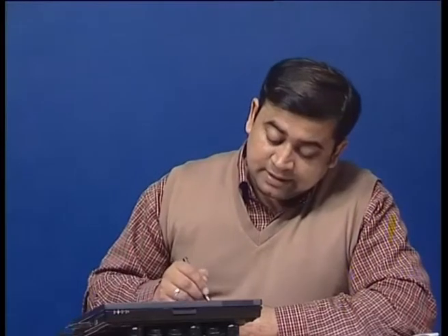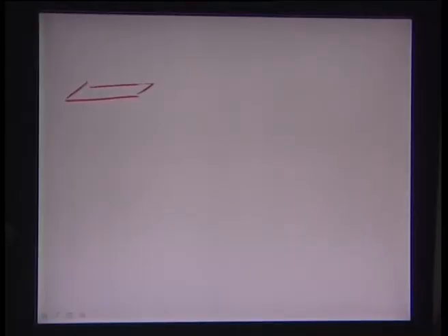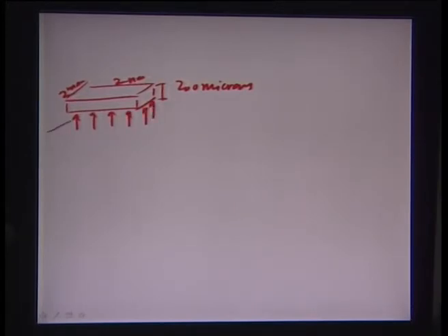So essentially we need to find out the thermal capacitance and the resistance in this case. First, let's draw the chamber. You have a 2 mm by 2 mm chamber, and the depth of this chamber is close to 200 microns, and we assume heat transfer from bottom to top. There is a set of micro heaters at the bottom of this chamber, feeding this particular chamber.